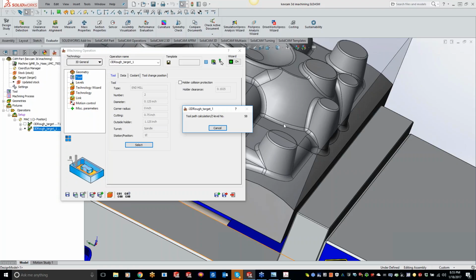So that you're not recutting the same material, you can go to your wall offset and increase it. Instead of saying 15 thou, you can say 16 thou, and it will leave that 16 thou on the wall, but it's not going to recut anything that was cut before. And like I said, it's more of a tolerance. We're going out several decimal places, but those decimal places go on forever. So if there's any little bit left over, it's going to pick that up and try to remachine it.